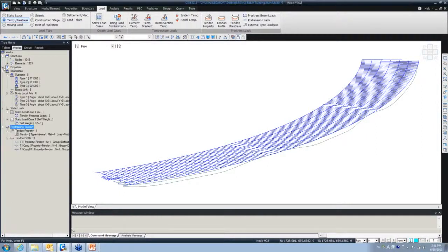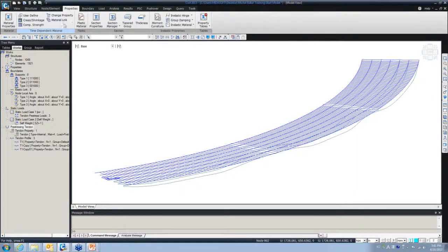Okay. So the method that I showed you today is using the Grillage model method, and we applied the tendon. I showed you how you can copy the tendon profiles and how you can apply the post-tension. Now another thing that is important in post-tensioning and pre-stressing is time-dependent analysis. To define the time-dependent material, we can go to the properties, and you can find them as creep and shrinkage and compressive strength. So here are the parts where you can find the time-dependent material property.